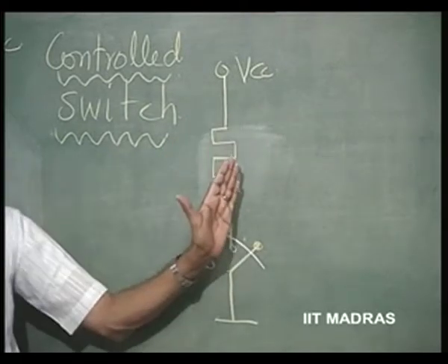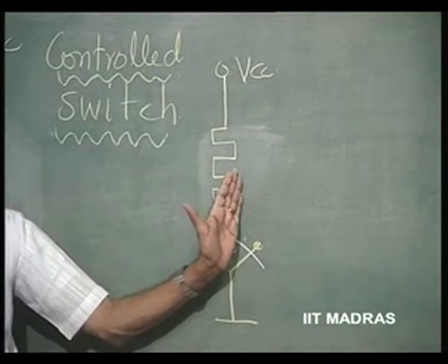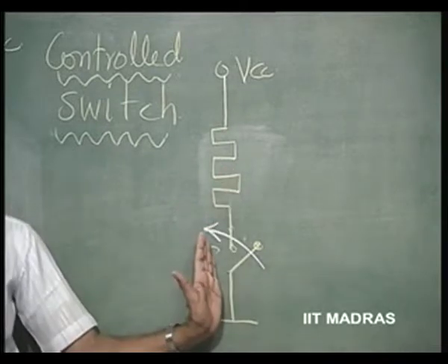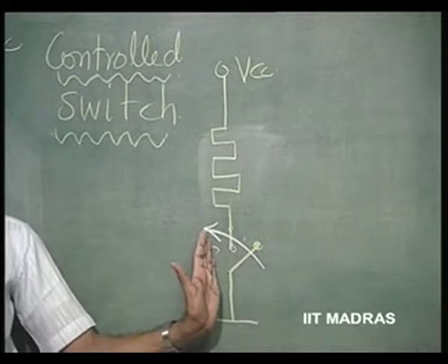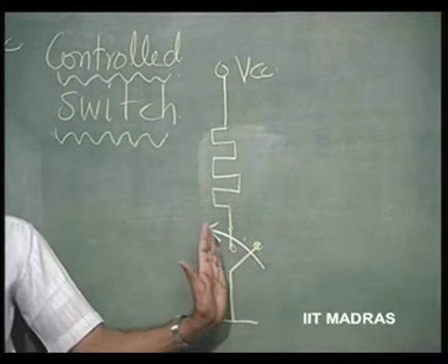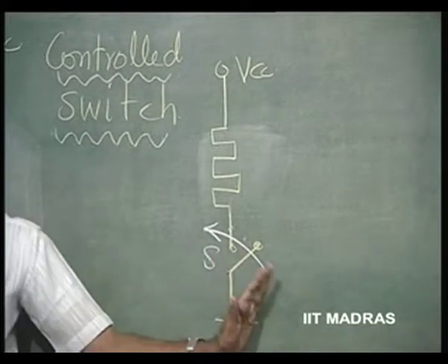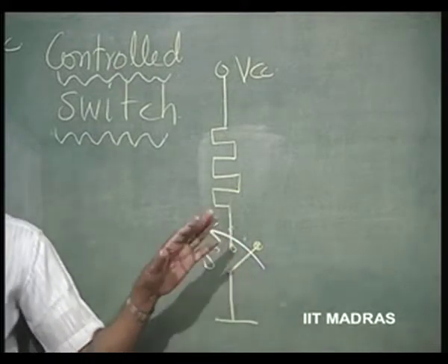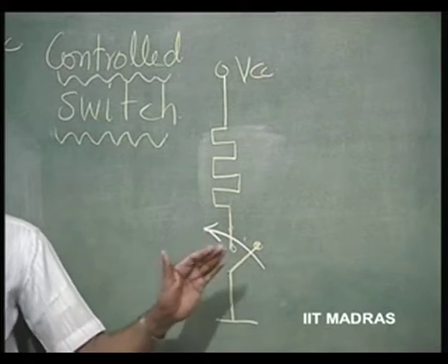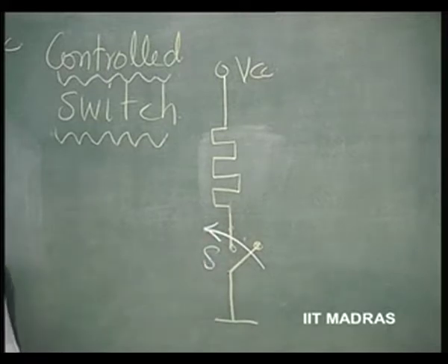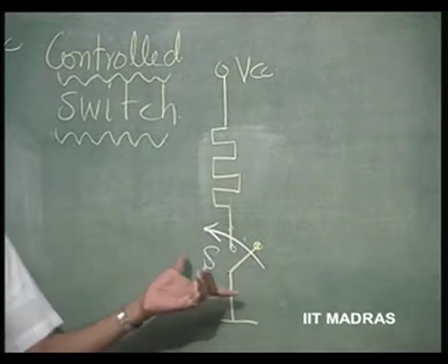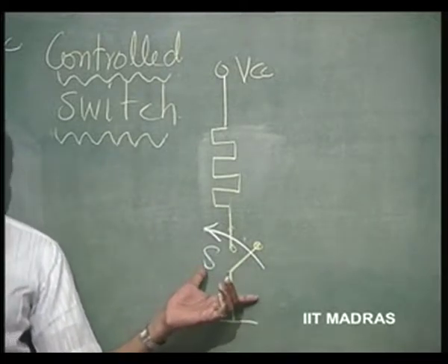So, this is how our soldering iron and all those things can function. I want to heat the heater element by connecting the power, and as soon as I reach the temperature, I want to disconnect the power. And again I will connect it, again disconnect it. I might connect and disconnect it in a controlled manner, so that the temperature rises up to a point and keeps on remaining around that point. So, this is an on-off controlling system, like our fridge.